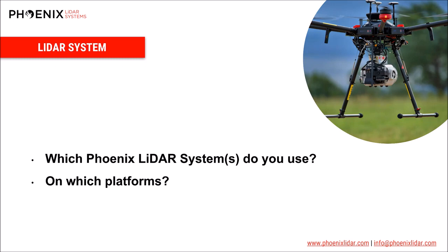So it depends on the aircraft. We fly it on 3 different platforms. The first one was the M600, and I got to say a lot of heads were curious why we were putting it on it, because I believe the M600 has a 6 kilogram payload capacity more or less. The LiDAR weighs 5 kilograms. You throw on a GPS antenna for the sensor, all these mounting points, and you get pretty close to that maximum. And we threw on the heavy batteries too.